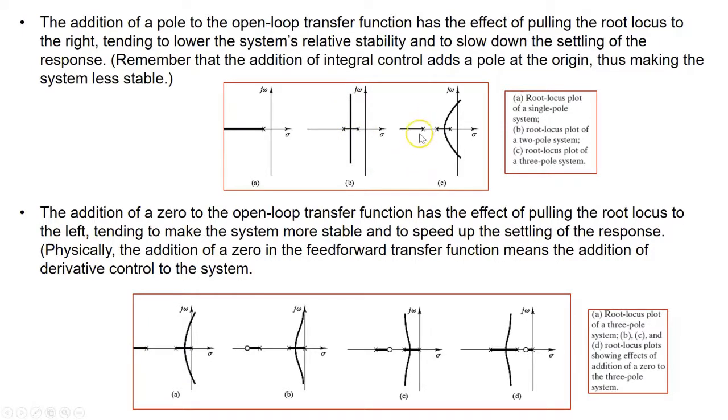And if I add one more pole, now what happens? Again, for these areas, the system, at least for those poles, shows overdamped behavior, but for these two poles that are now moving on these two branches, what happens? Again, underdamped, but with one difference with respect to B. Now, you see, if I move K to some large number, what happens? My root locus moves to the right-hand side of the imaginary axis, so the system becomes unstable.